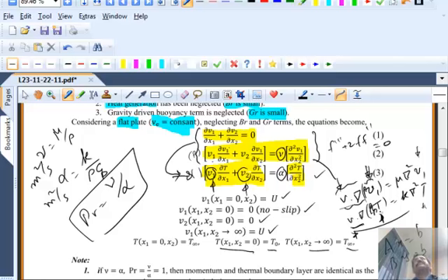It's an easy question to answer, because what you need to do is think about the two properties that determine this, alpha and nu. The kinematic viscosity nu characterizes the ability of the fluid to transfer momentum in a transverse, perpendicular direction. And thermal diffusivity characterizes the material's ability to conduct heat. Both are molecular processes, but they don't occur at the same rate. And that's why we have different properties. For the same fluid, water, the thermal diffusivity is not the same as the kinematic viscosity.